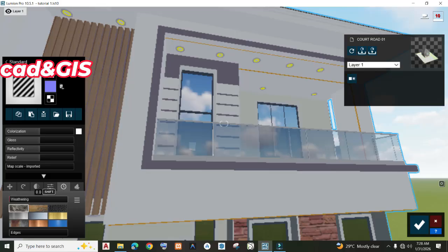you can go to these settings. Once you click on these settings, you see where they write this emissive. You can drag it up. It's going to increase the light. It's going to add an emissive property to our ceiling light. So the longer you drag it, the brighter the bulb will be, and your scene will become brighter. You should be very careful how you use it so that you won't give unnecessary brightness to your scene.